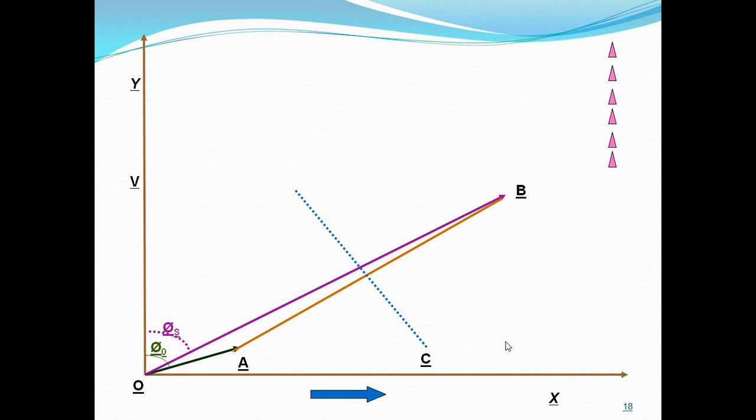Now with the same radius, don't change the radius, and B as center, draw another arc on both sides of the line AB, which cuts the previously drawn arcs. Now we got two points where the arcs cut on both sides of the line AB. Join these two points with a dotted line as shown.